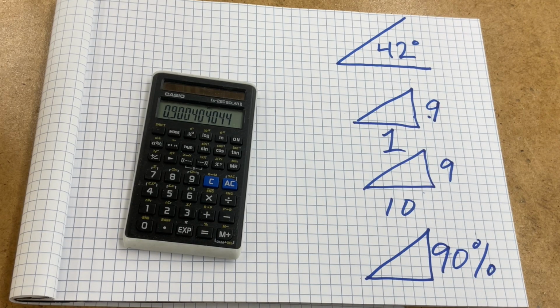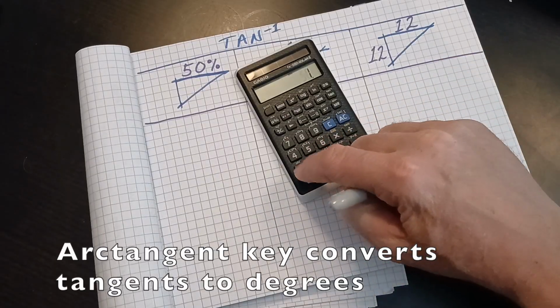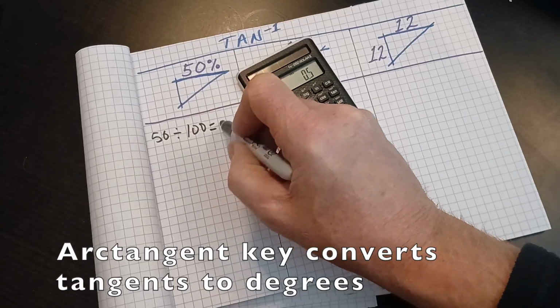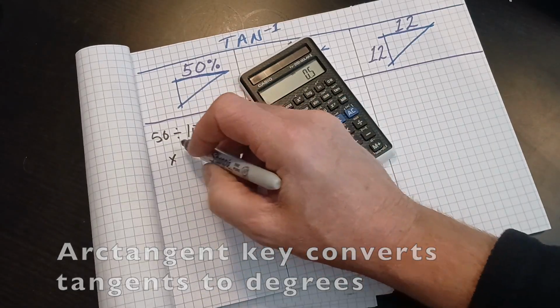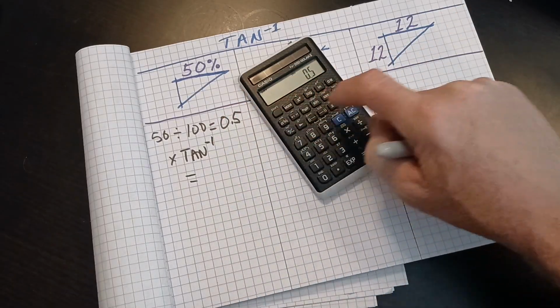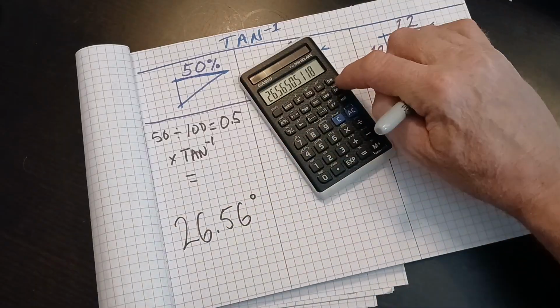Now, if your slope is given in rise over run, but you want to get it into degrees, use that tan to the -1 or arctangent key. For a 50% slope, divide 50 by 100 to get a tangent of 0.5. Hit the arctangent key and it shows 26.5 degrees.